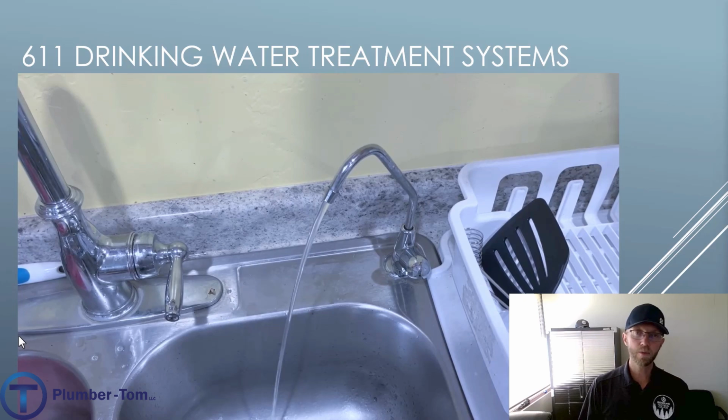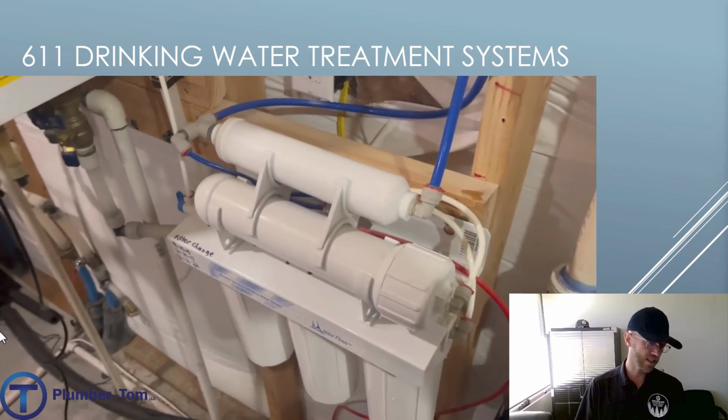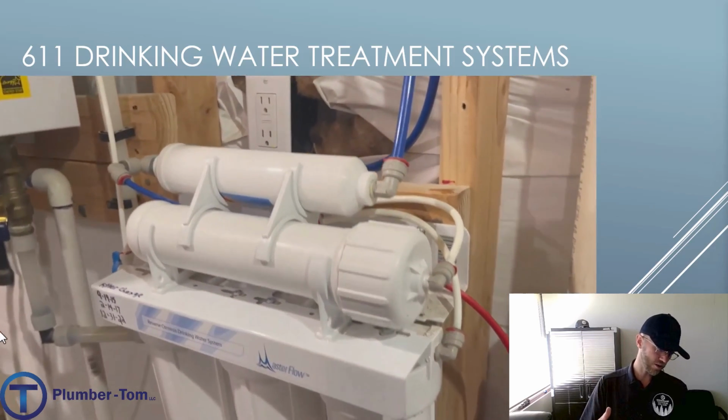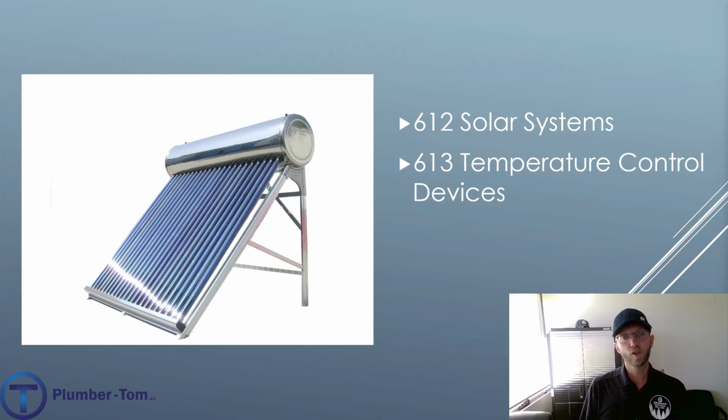In 6.11, we look at point of use drinking water systems such as reverse osmosis. It basically tells us that we have to meet certain standards of water quality and that the waste should discharge through an air gap. Section 6.12 refers us over to the International Mechanical Code for more information about water heating solar system, whether that's for heating, domestic hot water, swimming pools, whatever else. The mechanical code's going to have more information about that. And finally, 6.13 talks about temperature control devices, stating that it has to meet a certain standard, the ASSE 1017.